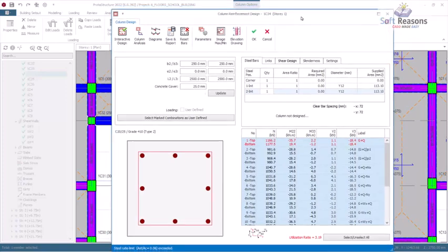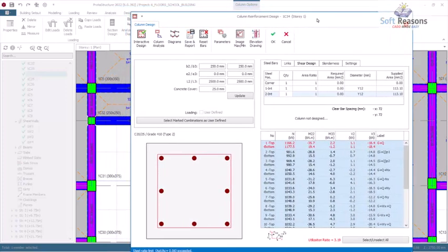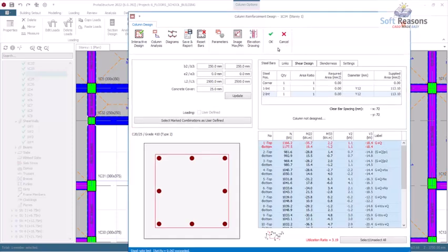All right. So what we will also look at while we are designing is the beam sections. We have to pay attention to the beam section. Like this column, we have it to be 250 by 250. You notice the column is now smaller than the beam sections, which is not modular enough. This particular column is not modular enough. So for the sake of our beam sections at this floor, we will have to change the sections to 300 by 250, so the beam can flush very well.